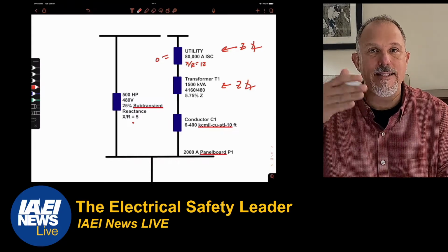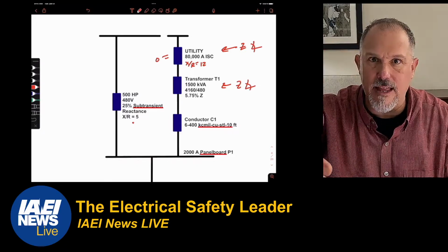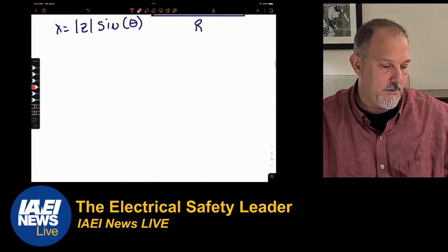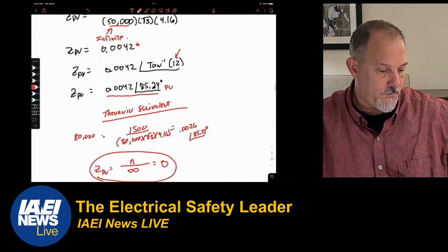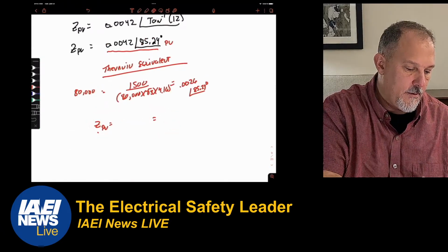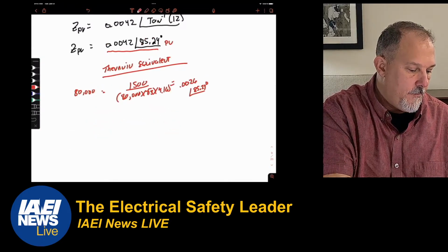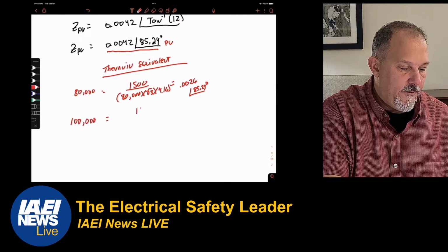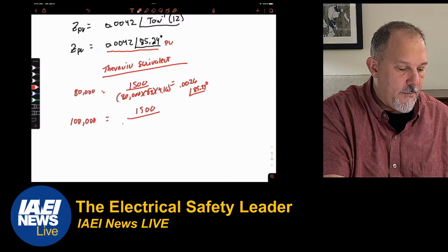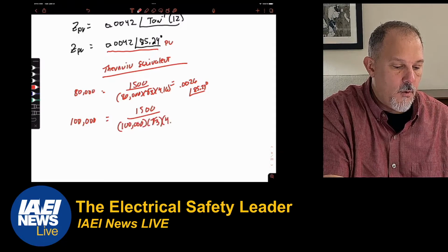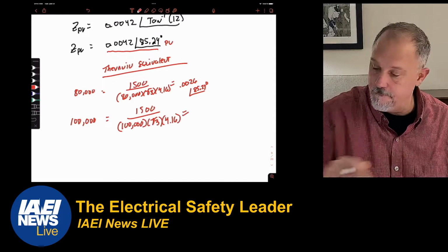The moment I say 50,000 amps or 80,000 amps or 100,000 amps, let's do 100,000 amps. 1,500 divided by 100,000 times the square root of 3 times 4.16.